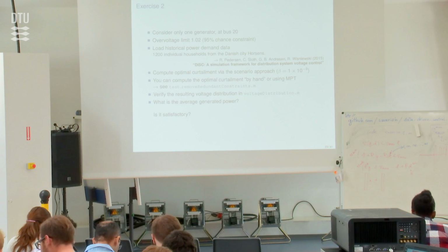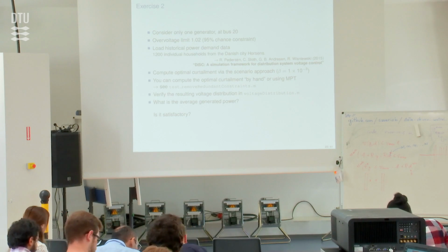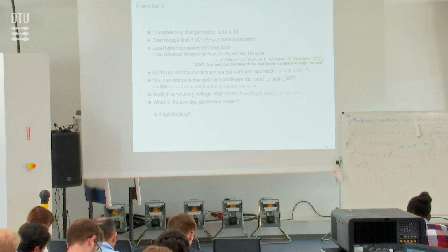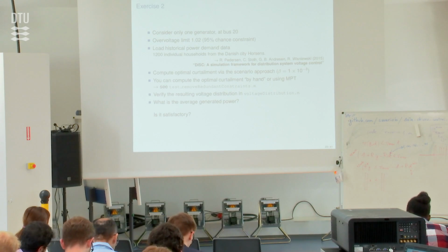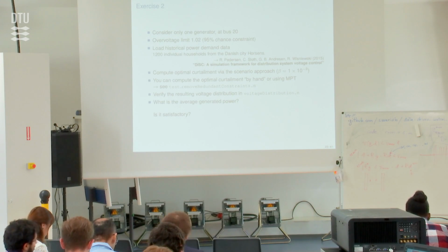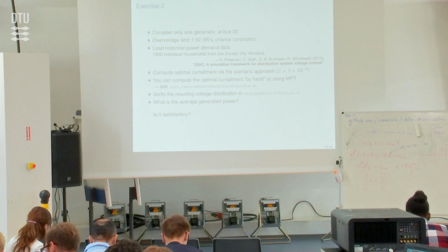And D. Exactly. So for example, if you have one sample where there was a large demand in a node close to the substation, that's not worst case. Maybe the worst case is a relatively small load, but very far away. So you need to compute the minimum of RD. Now, in this case study, should we calculate R or do we have it? No, R is already here. You have it from that line. Yeah, I did it right.